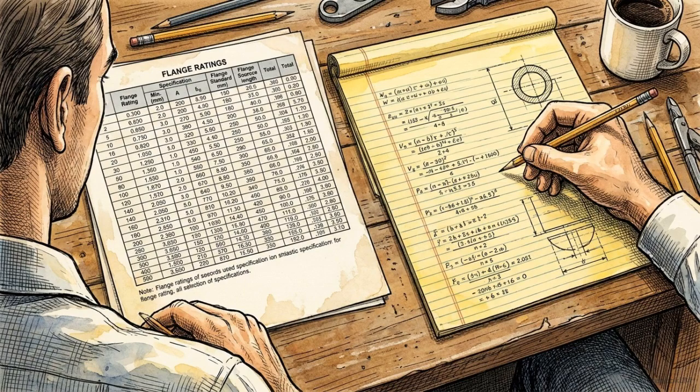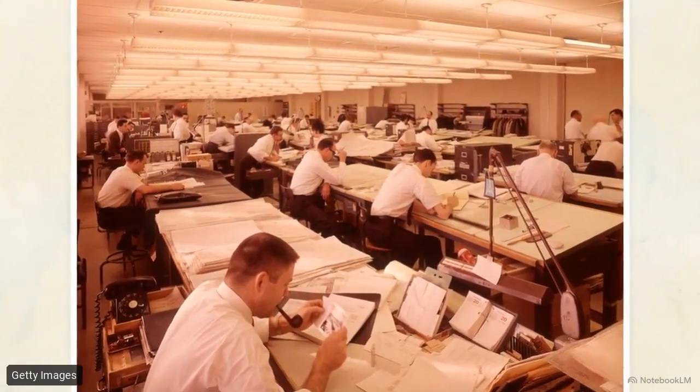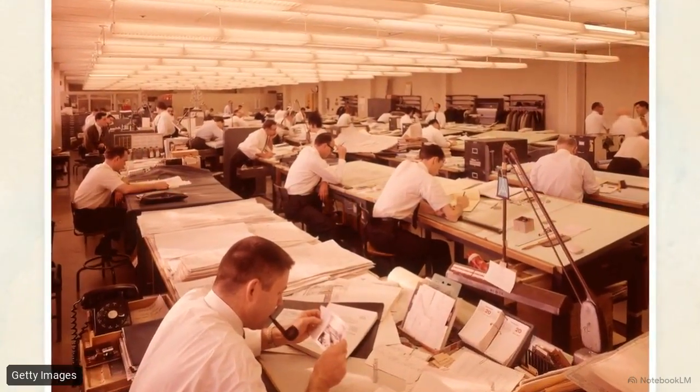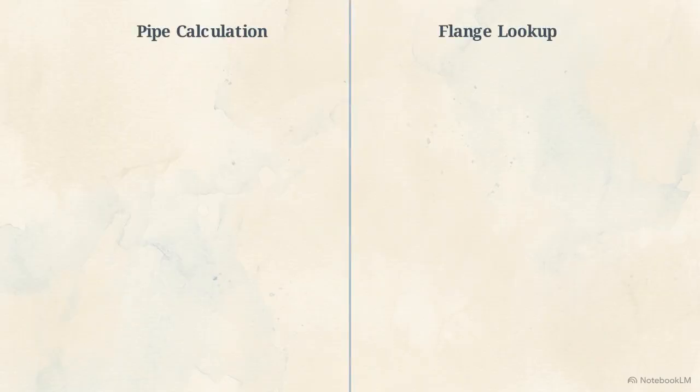The published codes have done the mathematical heavy lifting for flanged joints, but they demand the engineer prove the physics for the straight pipe. This theoretical workflow translates directly into applied design during the engineering phase of a major industrial project. Imagine a pipeline designed to handle an internal fluid pressure of 10 megapascals at a blazing 300 degrees Celsius. This environment requires a parallel workflow to properly size system components.